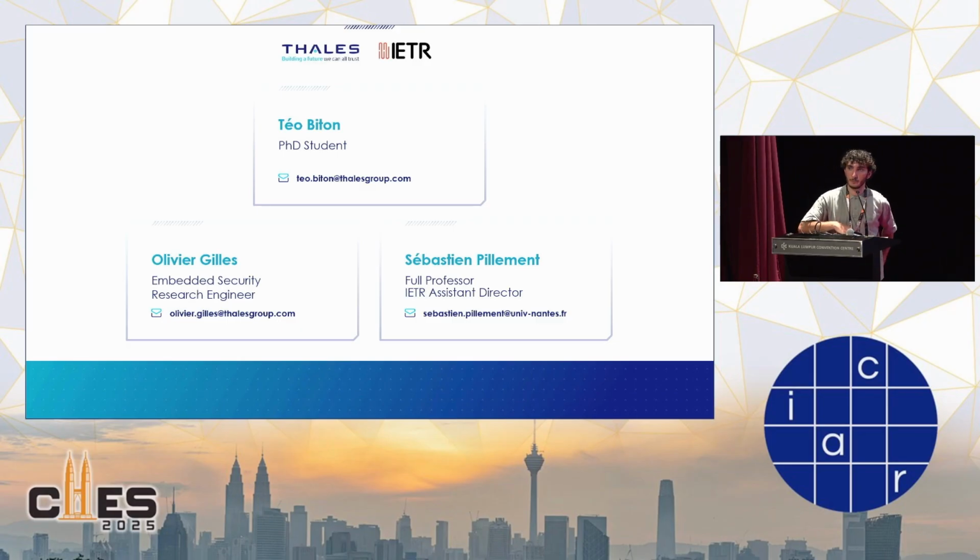So for a proof of concept, we didn't use any tool to inform the software that core rewinding was implemented. But if we're taking a more industrial approach, obviously we didn't test every application that is out there. The properties that we are based on are supposed to be respected by the compiler, but probably it's not the case for every application. So if we're thinking more industrial, maybe in fact there would be a need to know that core rewinding is implemented to avoid false positives, for example. But as part of the proof of concept, we were able to boot Linux and execute our benchmarks without knowledge that the security enhancement was implemented. Okay, thank you.